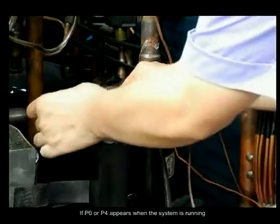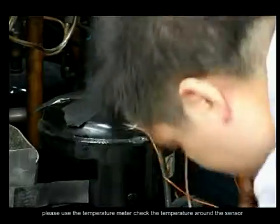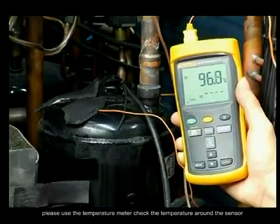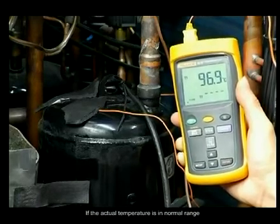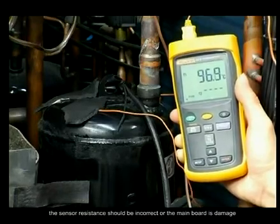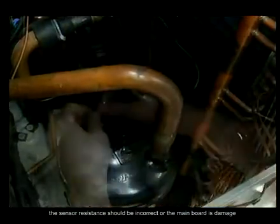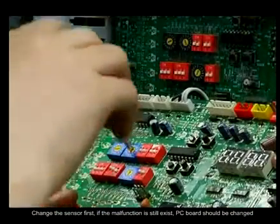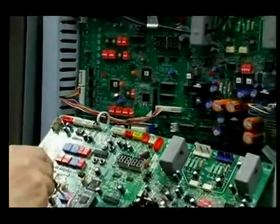If P0 or P4 appears when the system is running, please use the temperature meter. Check the temperature around the sensor, and see if it reached the protection value of 120 degrees Celsius. If the actual temperature is in normal range, the sensor resistance should be incorrect, or the main board is damaged. Check the sensor first. If the malfunction still exists, the PC board should be changed.